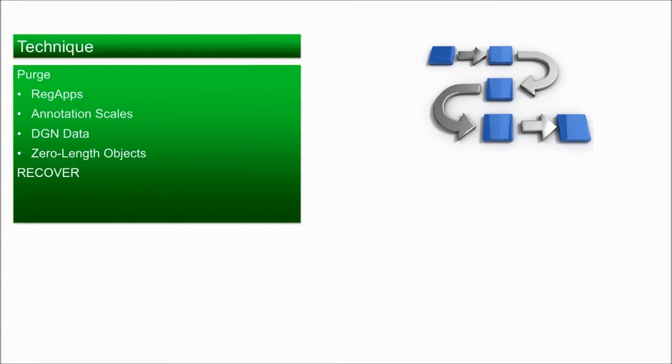The AutoCAD recover command. Occasionally, a file will get somewhat corrupted, but it doesn't necessarily manifest itself in that you can't open the file. Sometimes drawing corruption is fairly subtle, like a slowdown in your drawing, or maybe a style doesn't quite look right, or something like that. The recover command is a fantastic command to use. Make sure you use the recover command on your XREFs as well. If you have a drawing with a few XREFs, really, you want to recover them all.